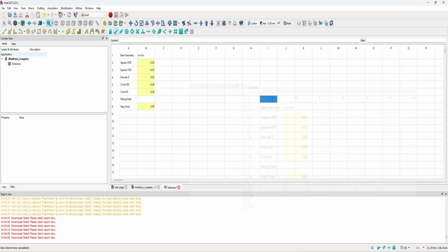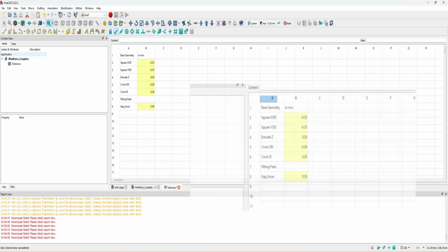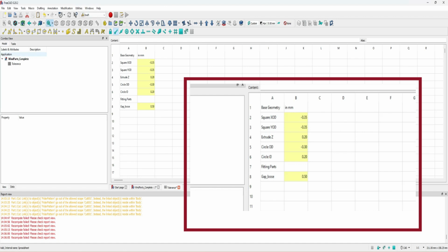So essentially what I do is I create a spreadsheet in FreeCAD, as you can see on the screen here. And within the spreadsheet, I set up my tolerances that I'm going to either expand my inside diameters or outside diameters or different dimensions by, and then I'll save those into the spreadsheet with aliases. And then within the actual application, when I'm creating the different shapes, I will add these dimensions to the actual numbers, the real life numbers, and that'll take into account the extruded portion of the print that goes over or under the normal dimensions for me automatically.